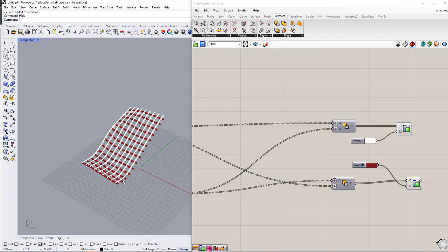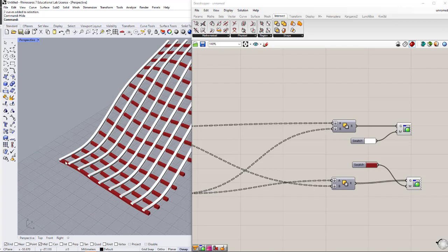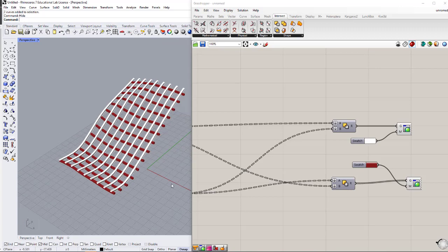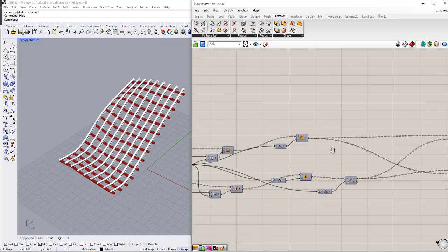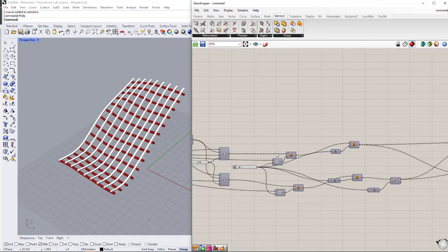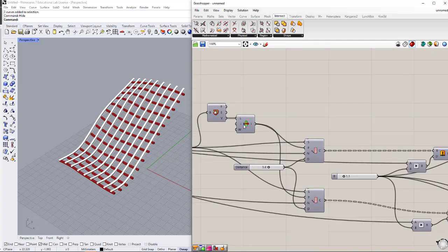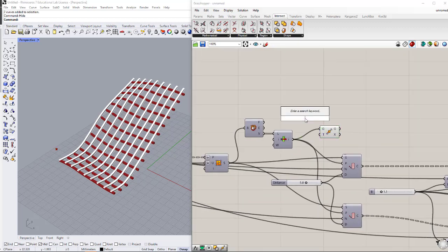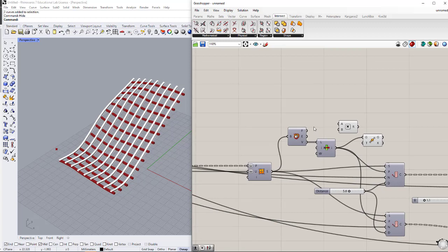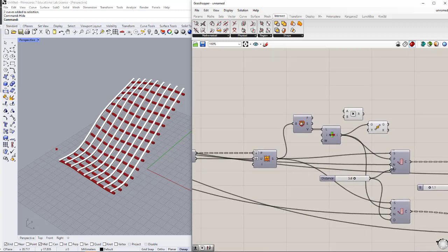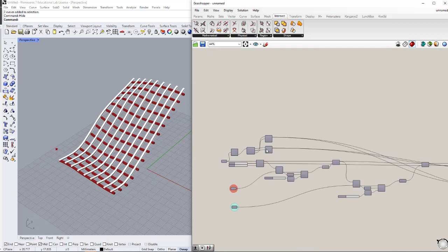And that's it. But you can also change where they start from, or if you want them to be extended in this part. And for making this kind of changes, you can just change this start point that you use for the contour. For example, in here, if I just use a move component and change it based on the vector that we also used for this direction, which was this one.